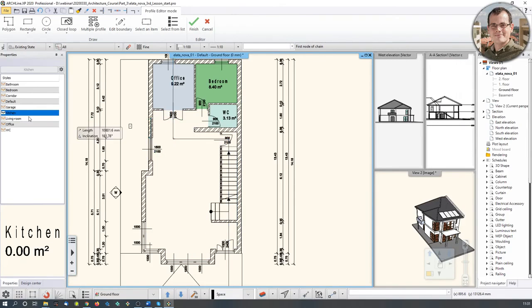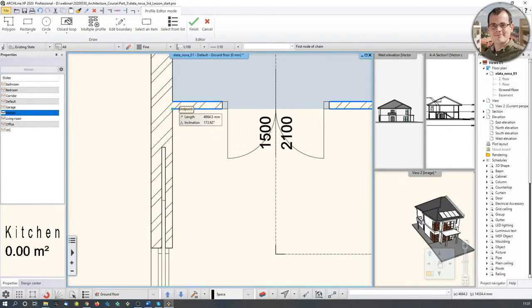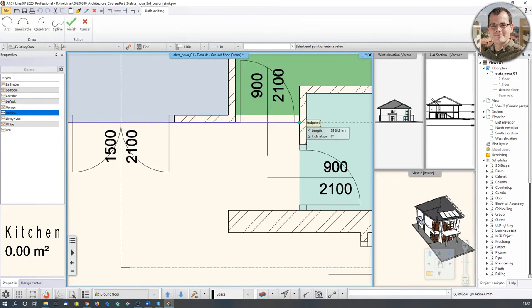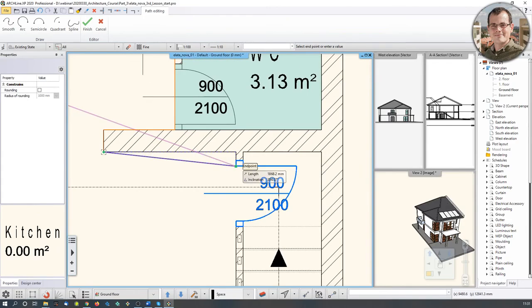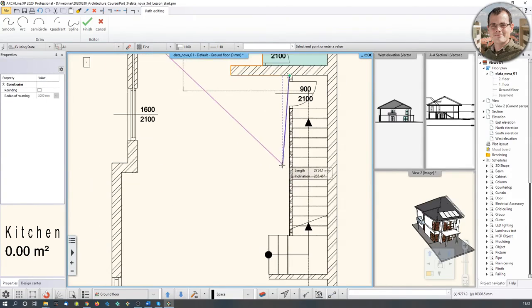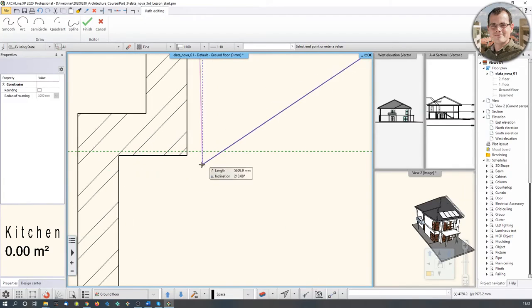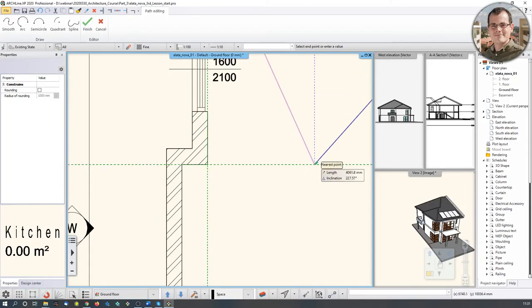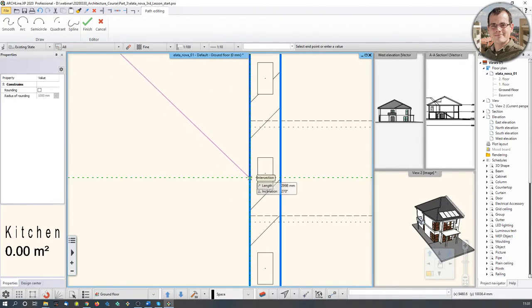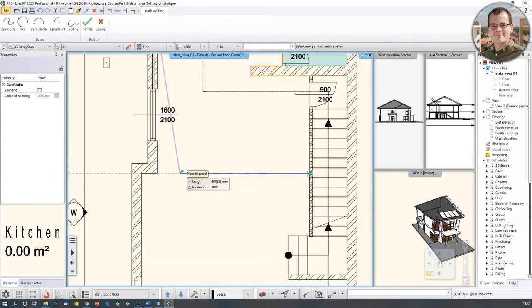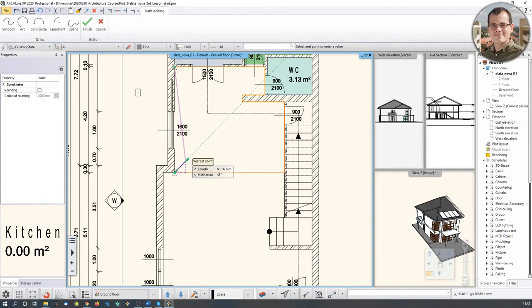And if I do that, first I define the role of this location, and then I can just sketch the polygon, any kind of polygon, by the way. And that way I can define how large this location actually is. Now, I want this line to go to this distance. How do I do that? I'm just going to hover my mouse to this edge. The green helping lines appear, and I'm just going to snap. You have to zoom in because this drawing is getting pretty dense. So I'm just going to click over there, hit enter.